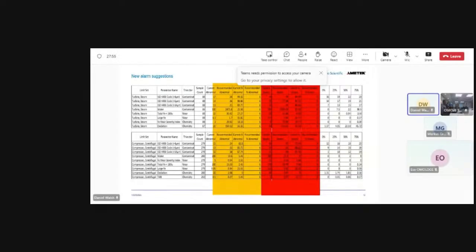When the alarm limit is too low and everything is an alarm, you can't prioritize. So I'm saying that yes, you're going to have to raise your alarm limit to address the top 3 to 6% of your problems first, solve those, and then you can start improving and reducing your alarms later on. This is a key factor that has to be continually done for programs to get them into control.